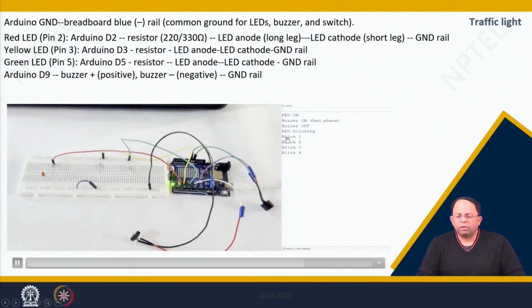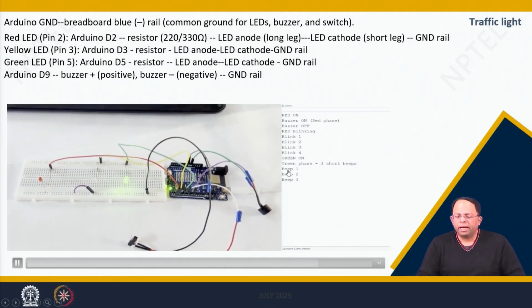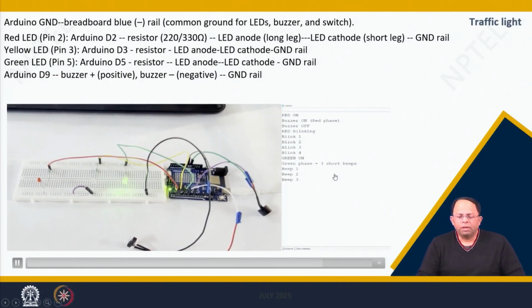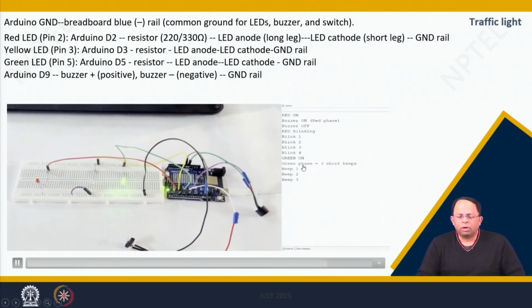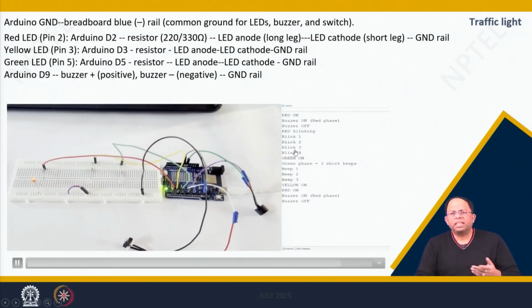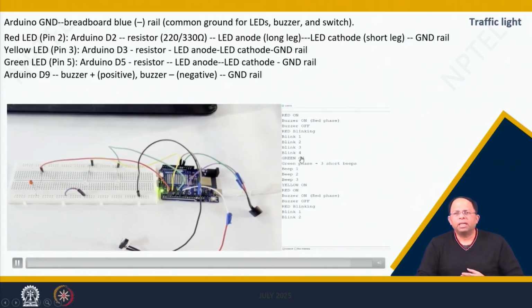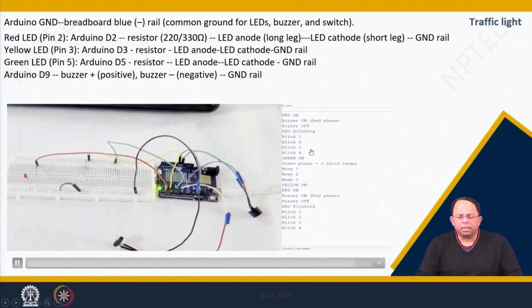And we can see the serial monitor over here. Whatever is happening in the serial monitor, I have added that over here, and you can see as we are blinking, which one is blinking, red or green, we are also typing it out, and you can see in what sequence it is happening. This actually helps us confirm whether the commands we are giving are executed or not, so that we can check in the serial monitor, and if there is a mistake, we can correct it.